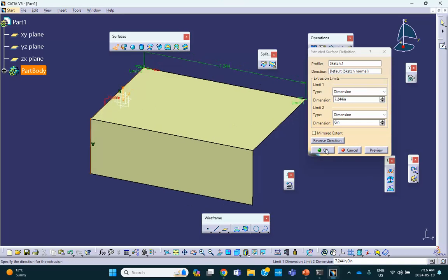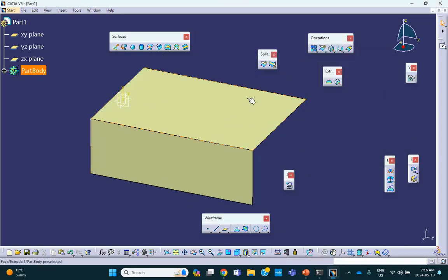So you can do it like this. There is no solid in it. So when you go and mesh this thing, you have to mesh it yourself. The solid is not meshed. You don't have to go through the business of deleting the 3D property and 3D element and then mesh it yourself. But you will mesh it yourself. Okay, this is just the beginning. We're going to do more of these later. Notice that I'm not joining it on purpose.